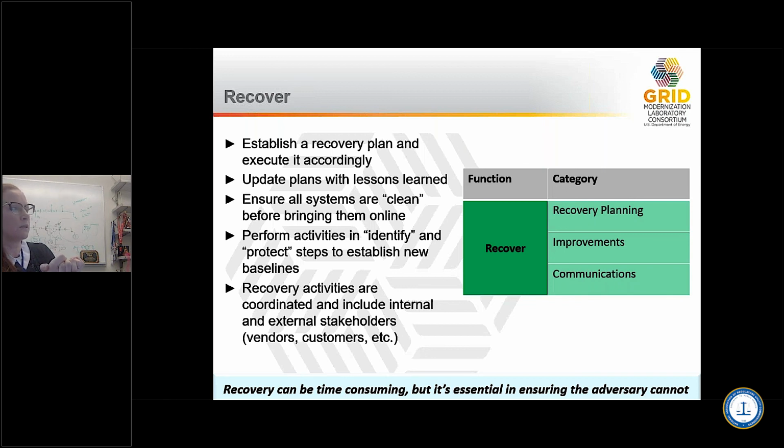The recovery plan, when it comes down to there being a cyber event on the grid, needs to be slightly different. I think everyone who's done safety training knows they talk about pausing and thinking about what you're doing. That's exactly what happens or should happen now when we're looking at responses to cyber events. There needs to be a pause where the power side knows exactly what they're reconnecting, but they have to pause and think about how they recover the system, clean up the system, so get rid of all of what's infected it. Don't just reconnect and hope for the best, because you're probably just reinfecting everything, or a lot of things.